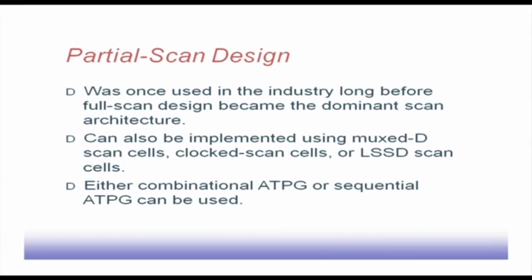So, some partial scan architecture stayed there. That continued, and after full scan came into the picture, even then partial scan was used in many cases. It can also be implemented using masked D scan flip flops, clocked scan flip flops, or LSSD scan cells. That does not make any difference. Now, what happens is that some of the flip flops or latches are converted into their scan counterpart. So, we can use combinational ATPG or sequential ATPG.